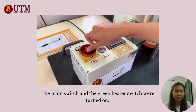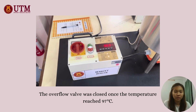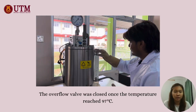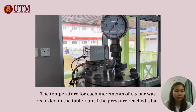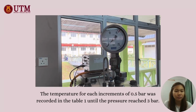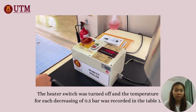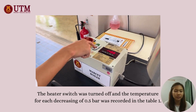Next, the main switch and the green heater switch were turned on. The overflow valve was closed once the temperature reached 97 degrees Celsius. The temperature for each increment of 0.5 bar was recorded in Table 1 until the pressure reached 3 bar. The heater switch was turned off and the temperature for each decrease of 0.5 bar was recorded in Table 1.